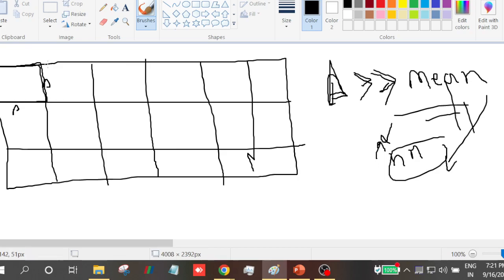Why this is required is because when we go very close to the mean free path of the molecules, the physics itself is different there. We need to consider different types of collisions, due to which different diffusions come into the picture. So our Navier-Stokes equations will not be valid in those cases, and separate physical models, which are much more complicated, need to be used. In many practical situations, this condition holds true, that the delta is much greater than the mean free path.